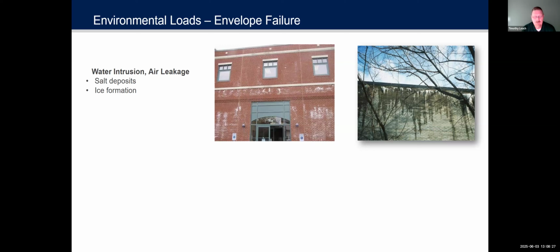Of course, obviously, there could be salts that are deposited on street level during the winter time, and that mixes with water and the water splashes up on the building. But you can also have effluents where there's other types of chemicals that are working into, in this case, this porous surface of the masonry. So anytime you have that sort of surface, you have to be aware of how that water is going to migrate, but it may leave behind other materials like these salt deposits.